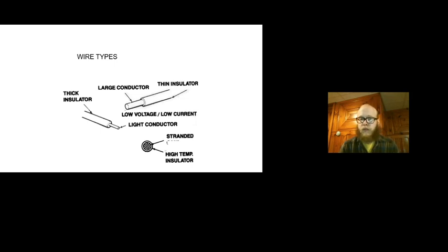It's more expensive than if we had a solid core conductor, just because there's more work that goes into making that piece of wire versus the other. But it's what we have to have, and broken wires happen in our harness that goes into the doors of vehicles very, very often. So even stranded wires are not quite up to some of the challenges, but it lasts for a long enough period of time that the manufacturers feel like they're putting in the best possible option.